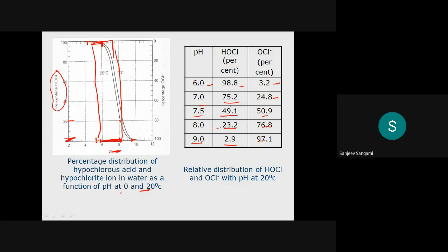Why we are speaking about the HOCl is that whenever you add chlorine into water, the formation of HOCl is very important. So if HOCl formation is rapid and if it is more, then we can say it is definitely a very important component in the chlorine disinfection process.